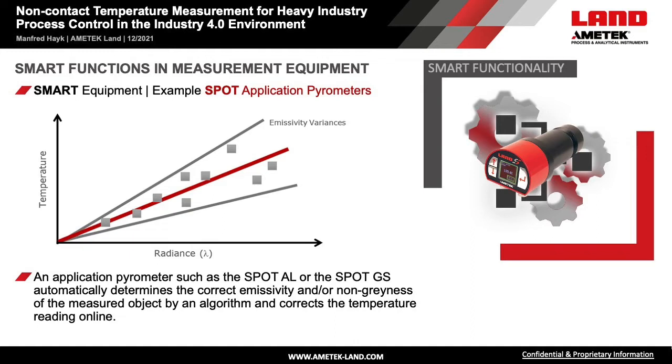In applications like those discussed before, in aluminium applications, where there may be different oxide layers on the aluminium surface resulting in different and changing emissivities, or in steel strip coating lines, annealing or galvanizing lines, where the surface emissivity is not only changing but also very low, application parameters are needed to compensate.